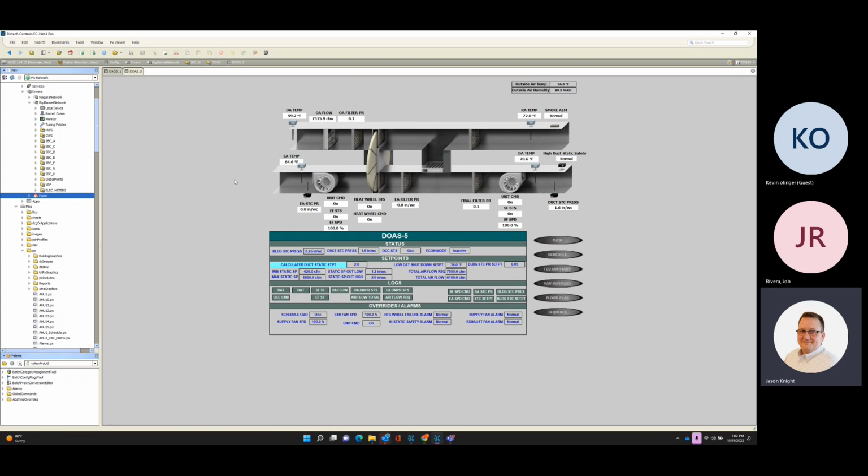You're going to suck in 10-degree air through this outside air duct and push it to every one of those fan coils. These fan coils aren't easy to get to. If you had to change a coil in one, it would be not only a massive amount of money to physically get up there and replace it, but also just the cost of the coils. So at the beginning of the project, I was just like, why don't we have any type of temperature safeties on these?